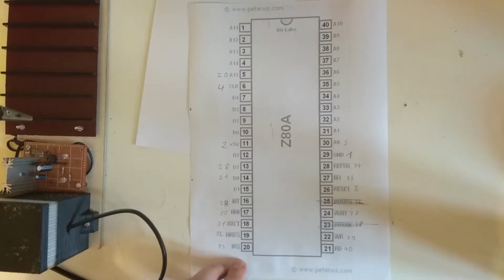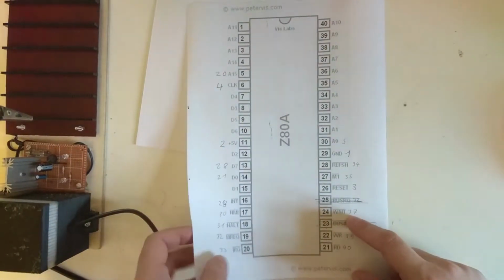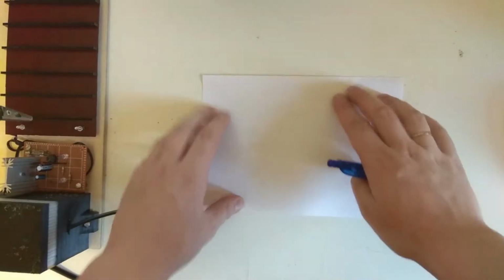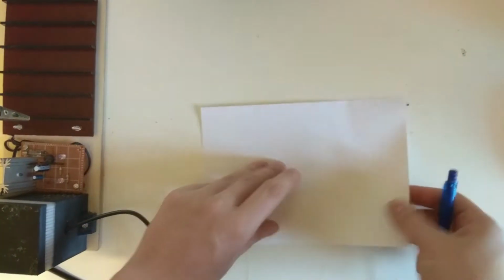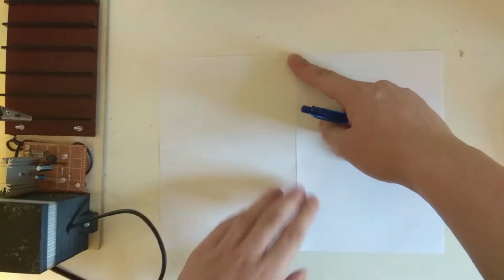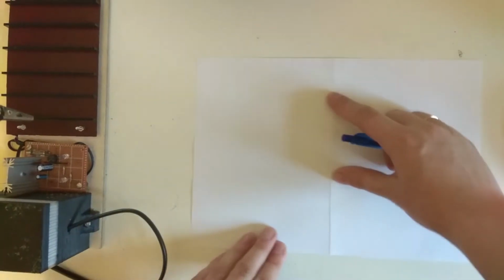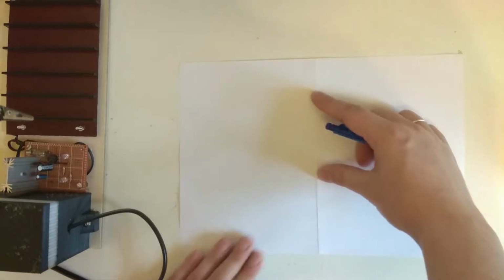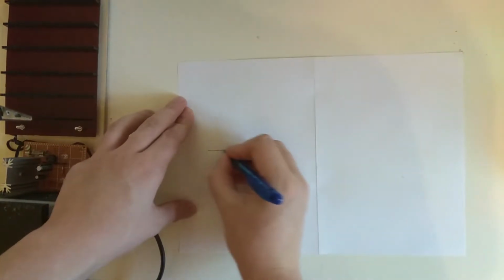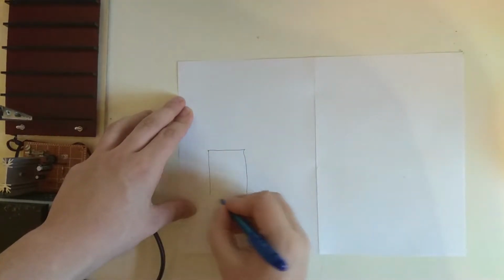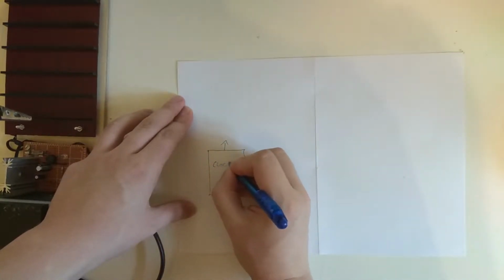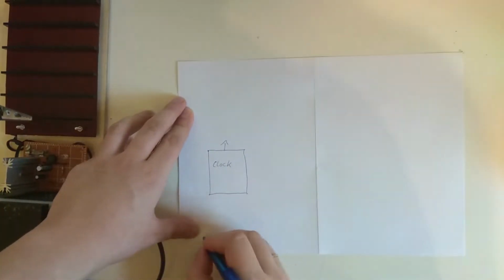Yeah. So with that decided, I think it's time we think about what we want to have on our first card for this Z80 computer. And I think the best thing would be, for the first card, to put a couple of utilities and also facilities for the front panel on it. And that means I want to have clock on this, the clock generation circuit. So just put a block diagram here and just write clock. And the bus is down here.